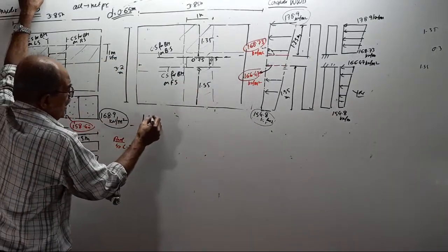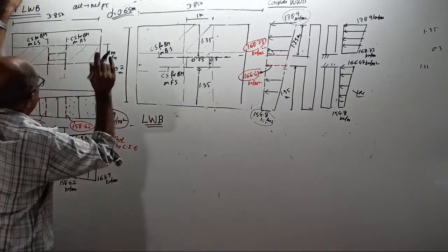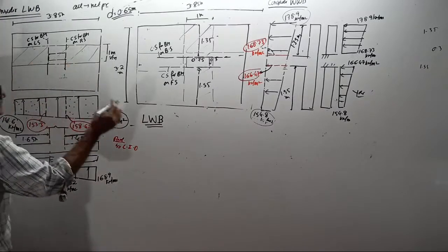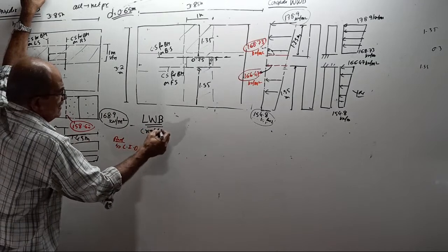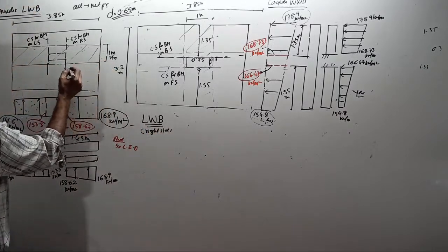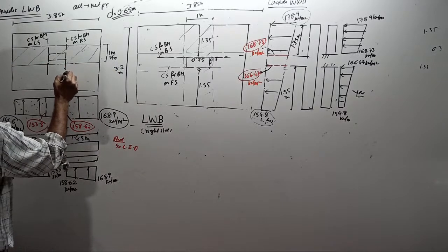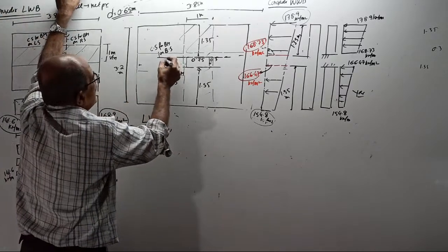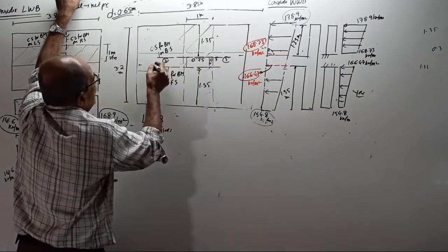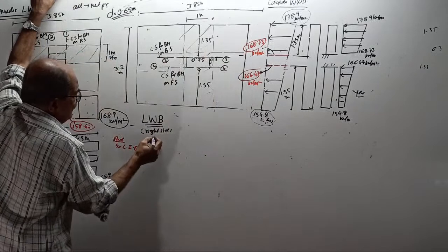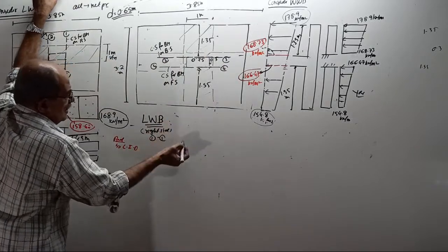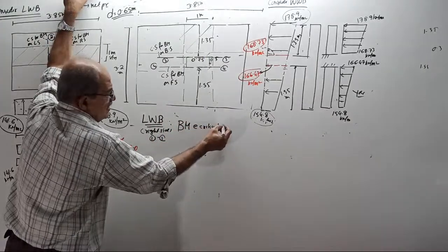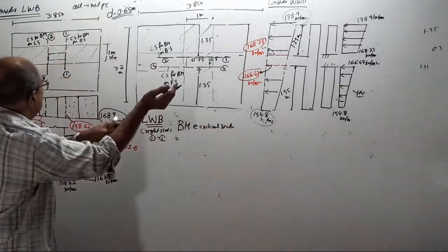First, lengthwise bending. Okay, start. Lengthwise bending. One cantilever this side, one cantilever this side. I will first consider the right side cantilever. Section 1-1, section 1-1, section 2-2. Later, I will tell section 3-3 and section 4-4. That is section 1-1. Start. Bending moment at the critical section, that is 1-1, equals,